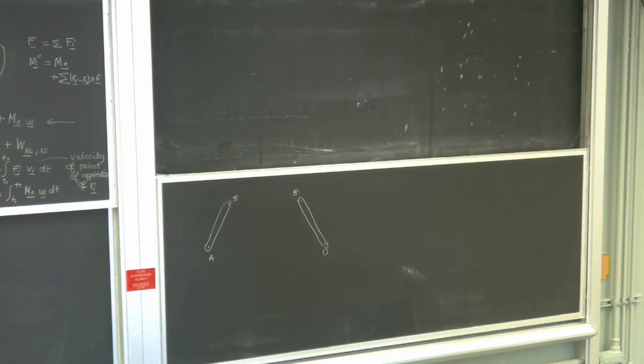In your free body diagram, you have to isolate the system. That's a moment. When you draw the free body diagram, you remove the support, basically. You isolate the system. So you need to remove that pin. Yes, you remove the pin, then the reaction force is going to show up.